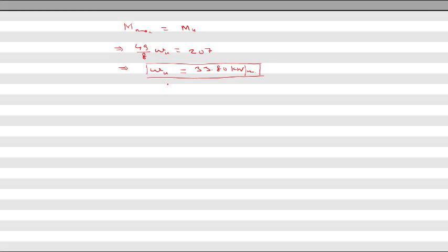Now basically I would like to know what is the working load which is going to be applied on the beam. So I can write load carrying capacity in service condition or working condition. So load carrying capacity in service condition will be how much? W divided by 1.5. Because when I say ultimate load, you have to multiply the load factor, the partial factor of safety of load, with the service load. So if I want service load, you have to divide the ultimate load by 1.5. And if I do this, I get W equal to 22.53 kilonewton per meter.